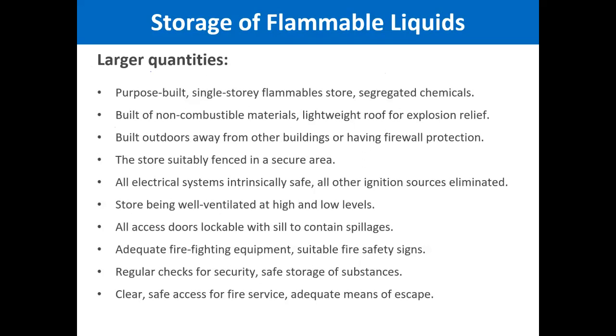When you are storing larger quantities, you need to have purpose-built single-story flammable stores, segregated from the chemicals as well. So you cannot store different types of chemicals together. You have to keep them separate. It should be built of non-combustible material, should be lightweight as well, and an explosion-proof roof should be there. Built outdoors away from other buildings. The store should be suitably fenced in a secure area.